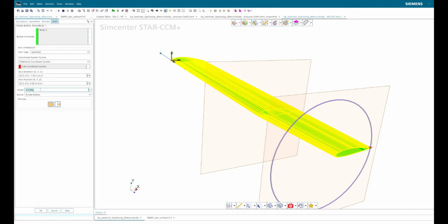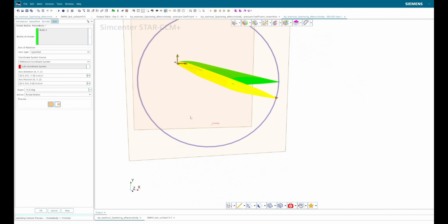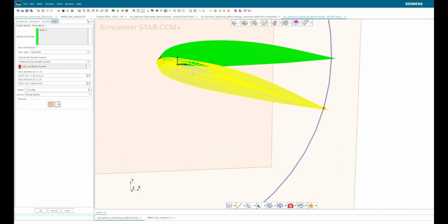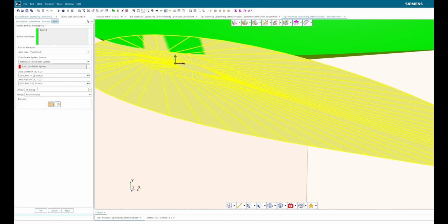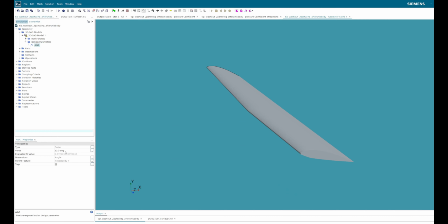At first, I made a mistake that caused the calculated CM to be consistently incorrect. When computing the overall pitching moment, I didn't account for the fact that the wing rotates around the leading edge axis. I used the quarter chord point for all angles of attack, but this is only correct and valid when the angle of attack is 0. There are two ways to fix this. The first is to keep the wing fixed and rotate the incoming airflow direction. The second is to shift the wing's rotation axis to the quarter chord line. Although the first method is more accurate in principle, given my current workflow, I chose the second one.